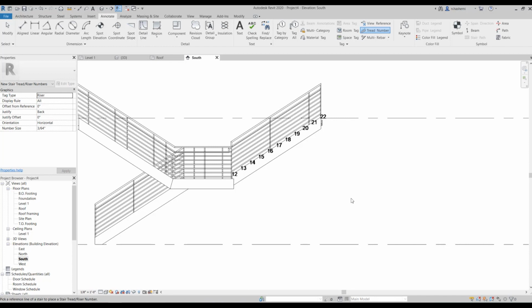Well, next I'm going to go over the railing section. This is just an introduction to the railing system in Revit, and it's good for you to have an understanding of different types and components of stair railings. Previously you saw that when we created this stair, the railing was added automatically, but we are also able to create those manually, for example at the edge of a mezzanine or a ramp or anywhere else.